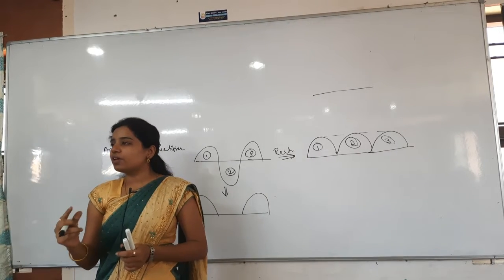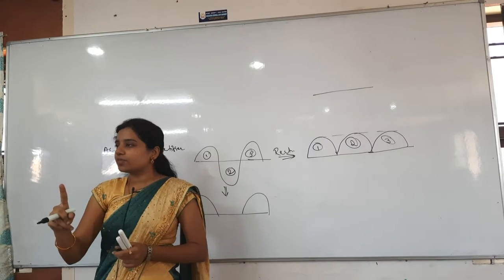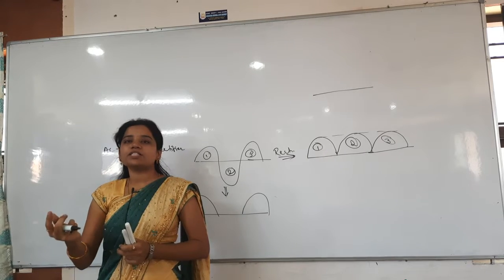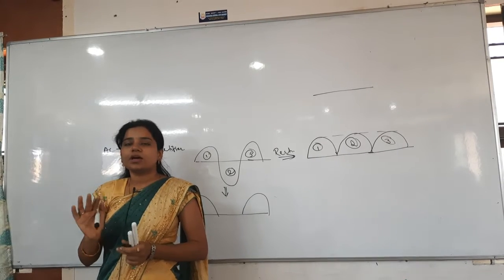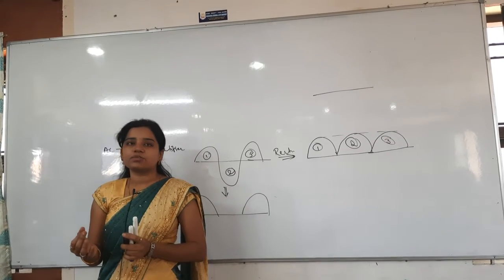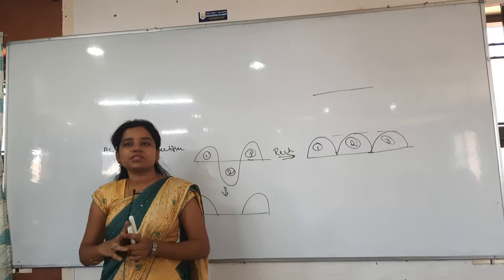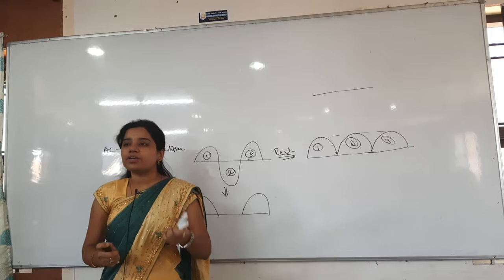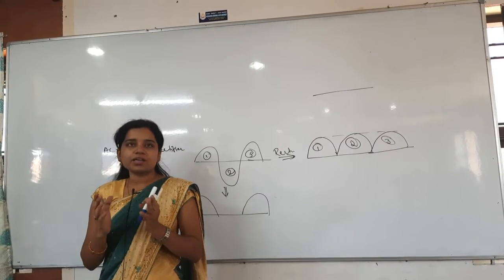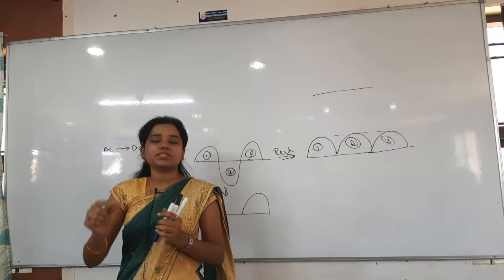In the case of the half wave rectifier, it will rectify only one half cycle at a time: in forward bias only the positive half cycle, in reverse bias only the negative half cycle. Also, RMS values and DC values will be there, everything will be there. You have to remember that. Even the efficiency will be there, and efficiency is important. For the half wave rectifier, efficiency is 40.6%. Just remember that for a half wave it should be near to 50, that is 40.6.